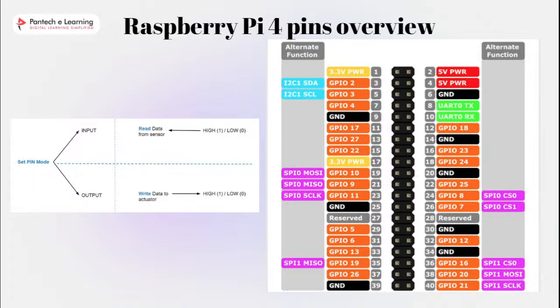You can use the 5 volt power pin from the Raspberry Pi to power the component, and then use any 3.3 volt GPIO for the communication, right? Simple. If you don't mix the 5 volt signal with the 3.3 volt signal, everything should be alright. If you want to go for 5 volt, just go with that. If you want to go for 3.3 volt, just go with that.